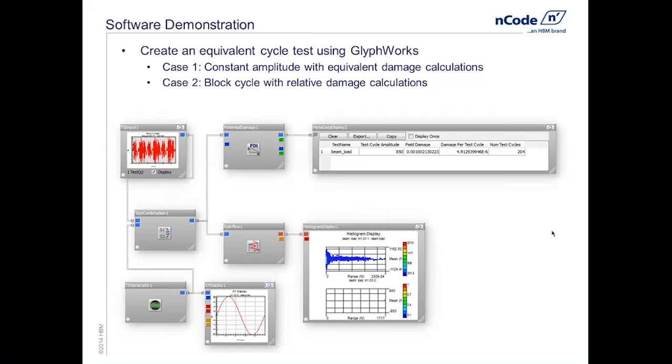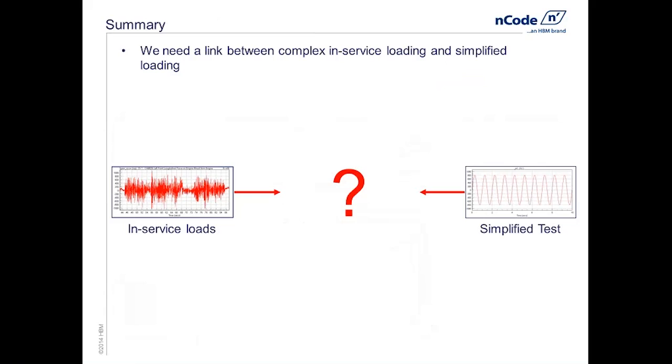Okay, clearly we were looking at forces, and if you know anything about fatigue, you would know that you can't take a force and go to an SN curve, because an SN curve should be stress and not force. If you do have stresses, you can do an actual damage calculation with an actual SN curve. If you choose to keep it the way that we did it right here, it's perfectly valid because the calculations that we're doing are relative, so it's an apples-to-apples comparison.